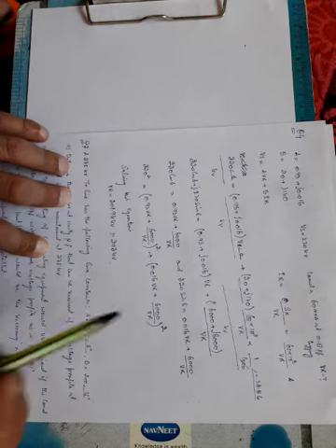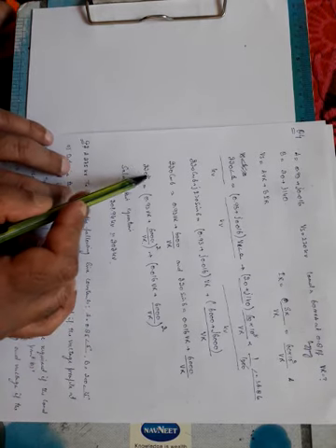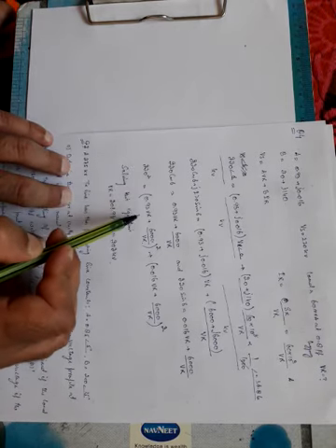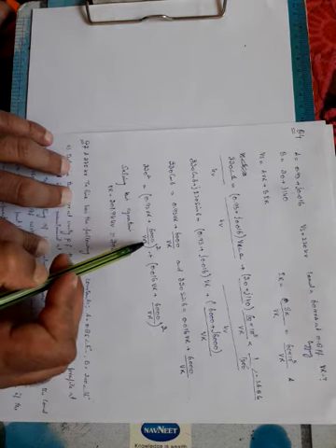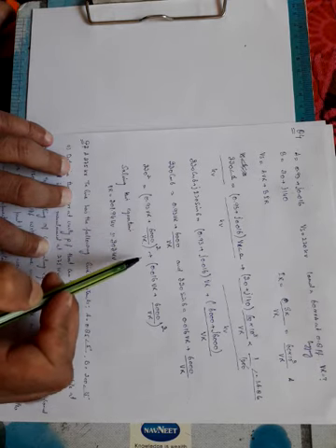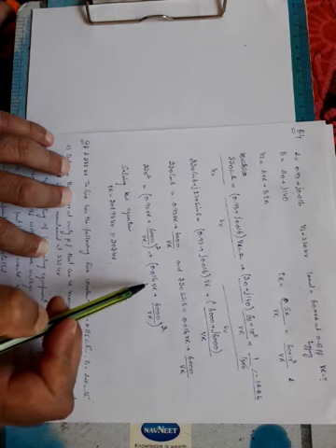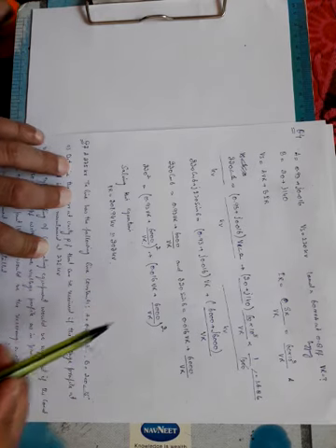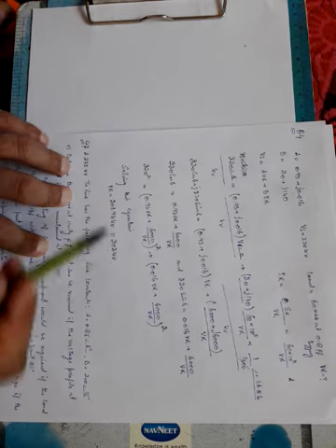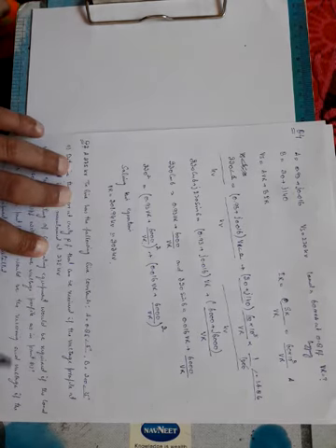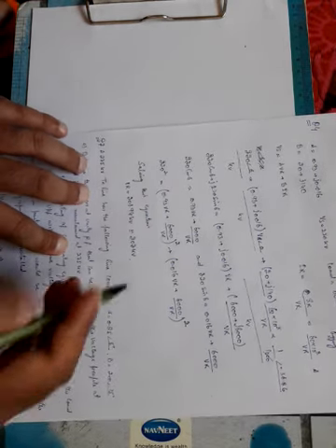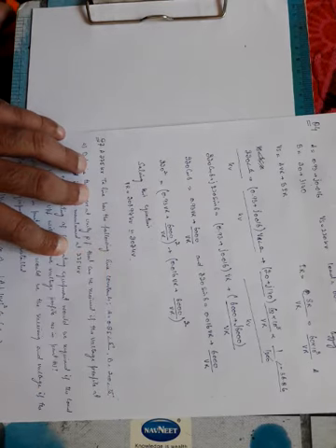It will be automatically eliminated. Then the equation becomes 220 square is equal to (0.93 VR plus 6000 divided by VR) whole square plus (0.016 VR plus 6000 divided by VR) whole square. So when we solve this equation, we get VR to be equal to 202 kV.